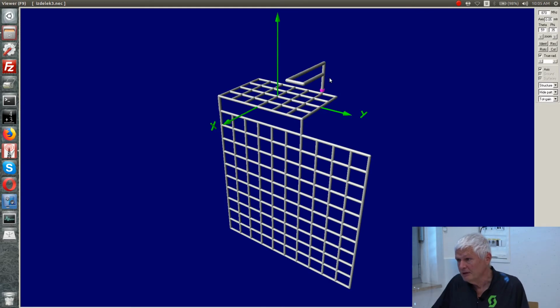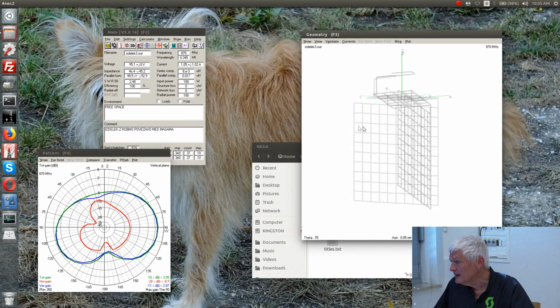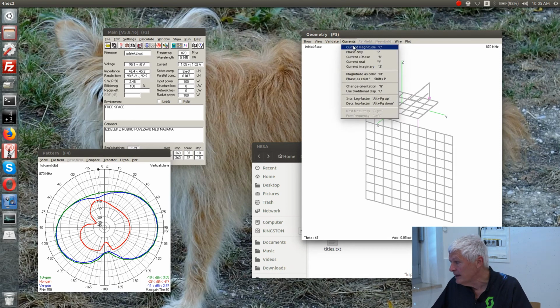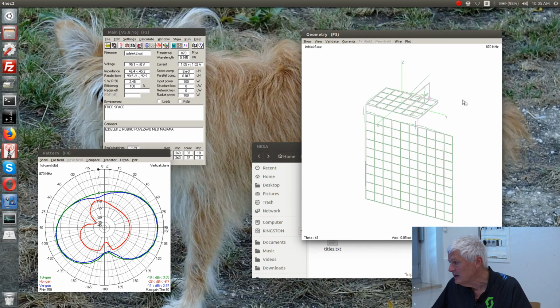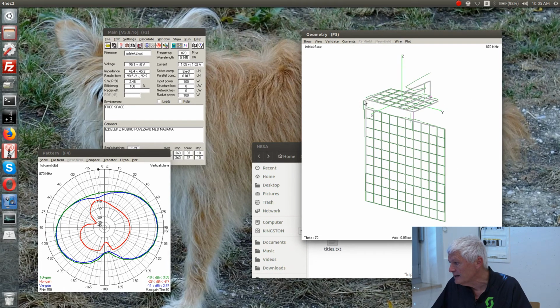Okay, what we can further do with ForNec2, we can further do some tricks and see where the current distributions are. So we can see where the currents flow in this structure. Current magnitude, and I can see currents. You see where I have the currents. I have very strong currents here in these two screws. I have very strong current in the antenna, but I have also some currents in this printed circuit board here.